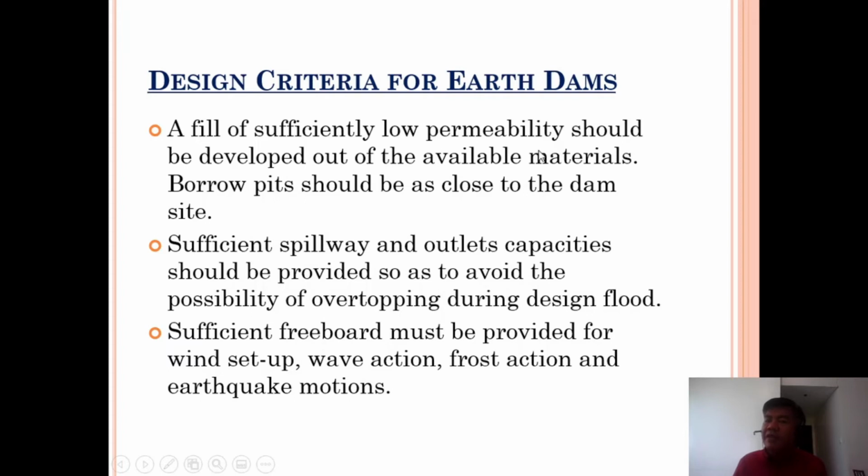So we need that fill with low permeability. Once you get the source, it will be tested in the laboratory and you are going to check the permeability. Of course, it is the value of K that will be inputted in the seepage analysis.